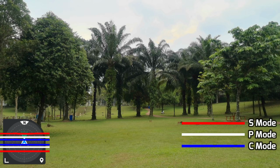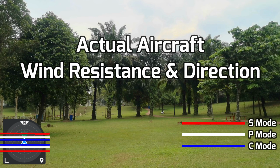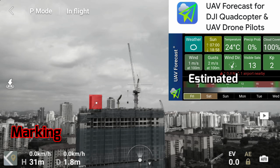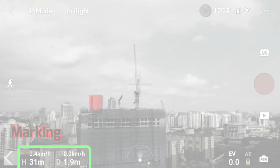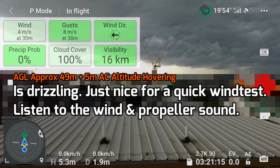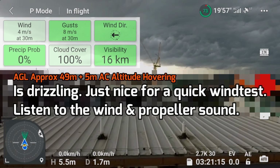Of course, we don't really bother how the aircraft flies or tilts in reality, but this tilting line will provide one very important piece of information: the actual aircraft wind resistance and direction. Previously, aside from wind forecast apps that only show estimated wind information and the famous strong wind warning, I used this flight telemetry to judge the wind speed and resistance in real time. Now, with this attitude indicator and the tilting line, we should be able to know the wind resistance and direction better than before, regardless of the aircraft's current location.